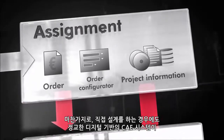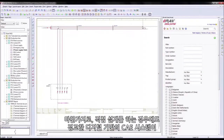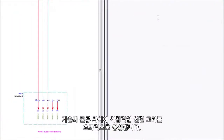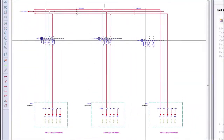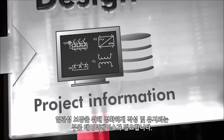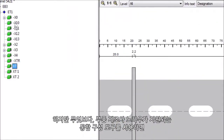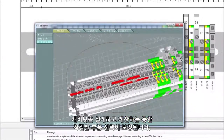In the same way, if you receive an order that you design yourself, a well-thought-through digital computer-aided engineering system effectively creates a direct link between technology and logistics, constructing intelligent blocks on the fly that automatically recognize and link up individual and up-to-date components. Of course, consistency is crucial, being ensured by a properly filled and maintained database of components. On top of that, using integrated configurator tools supported by the component vendor's know-how will ensure that you can only choose the correct components while designing and dimensioning your cabinet.